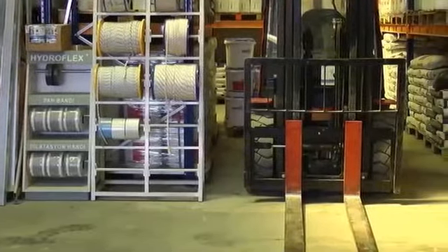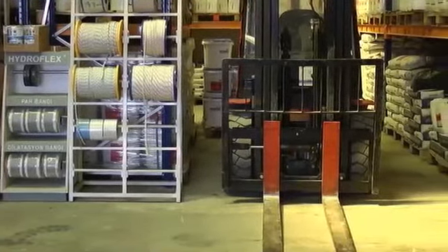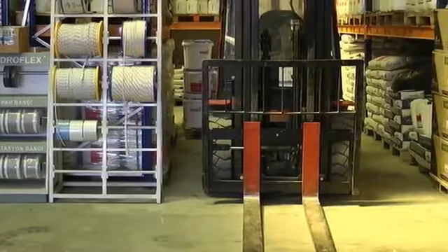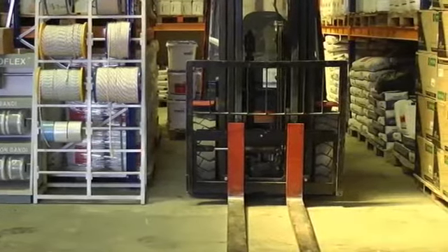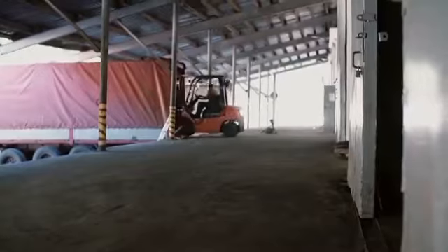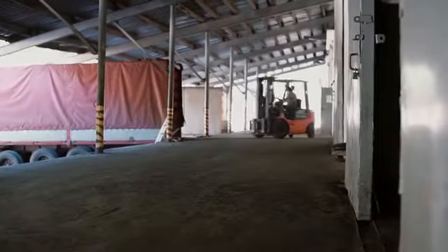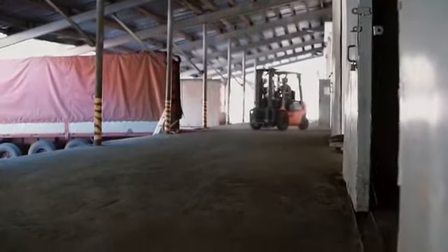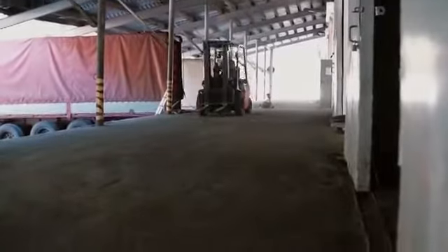When a forklift is left unattended, lower any load and neutralize controls, shut off power, and set brakes. Wheels must be blocked if the truck is parked on an incline. Keep a safe distance from the edge of ramps or platforms while on any elevated dock, platform, or freight car.